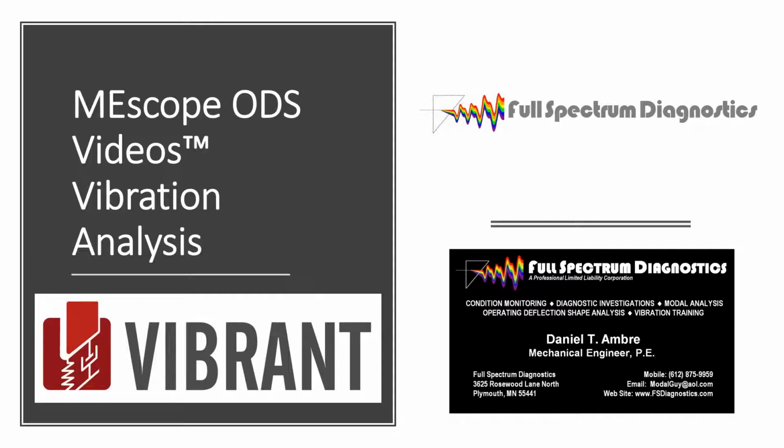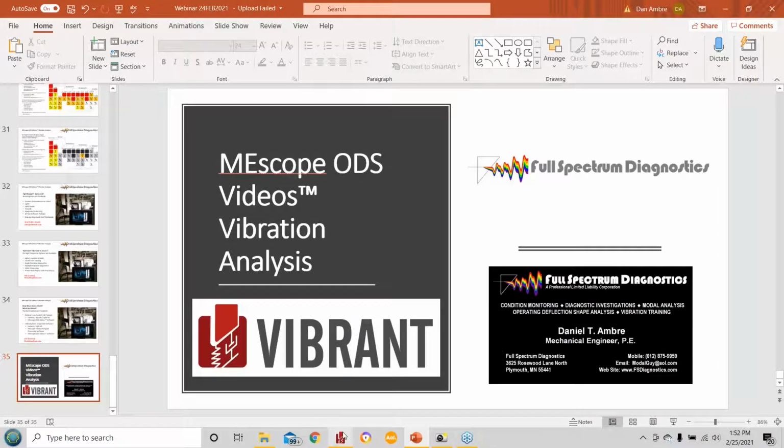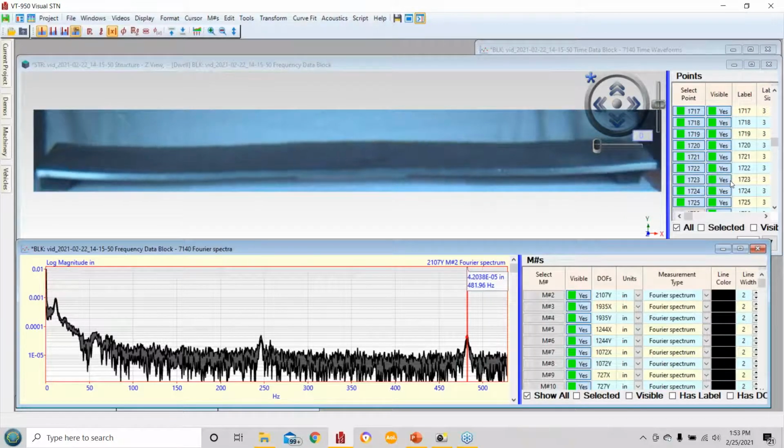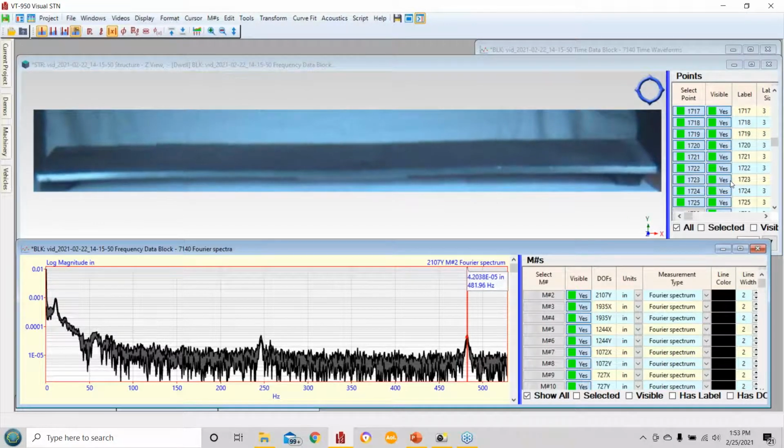If I took my plate and turned it on its side, I would just have a shiny uniform surface, and it wouldn't matter if my points were there or not. What really matters in this shot is what the edge is doing. That's the only way you can see what the mode shape is. From the top, or even at an oblique angle at 45 degrees, it's difficult to see what the plate's doing. But that's different from deflection at a point.